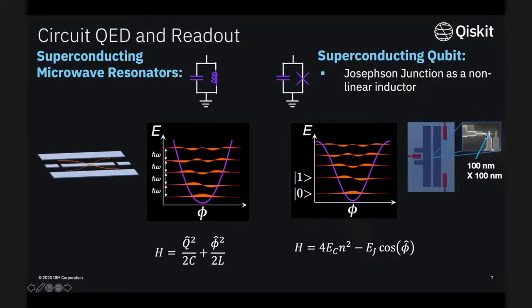Now, the Josephson junction can be realized in a lot of different ways. It is the only known lossless nonlinear inductive element. Most commonly in the context of superconducting qubits, the way that this inductor is realized is through a superconductor-insulator-superconductor barrier, where the superconductor is aluminum and the insulator is aluminum oxide. This happens to just be something that gives the best quality of junction. This is one area of research in which people try to engineer different sorts of Josephson junctions that have different properties, and it can end up being a very exciting field in its own right.